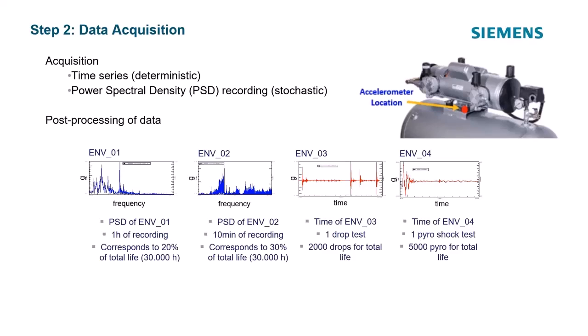But you're going to see that when we input PSDs, we have to make some assumptions about the amplitude distribution at a frequency line, and that assumption isn't always correct, and I can show you how that comes out in some data. And remember, we want the input into the structure. That's our must-have. Nice to have is on the structure itself.